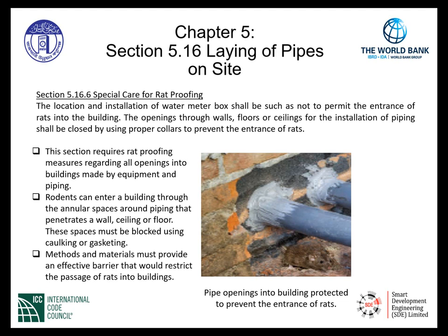The picture shown off to the right indicates pipe openings into a building that are protected to prevent the entrance of rats. This is a packing material that's packed into the annular space and sealed with a durable waterproofing finish that is designed to prevent the entrance of rats into the building. This is so important because we want to keep the people safe and healthy within the buildings and keep rodents out of the building.